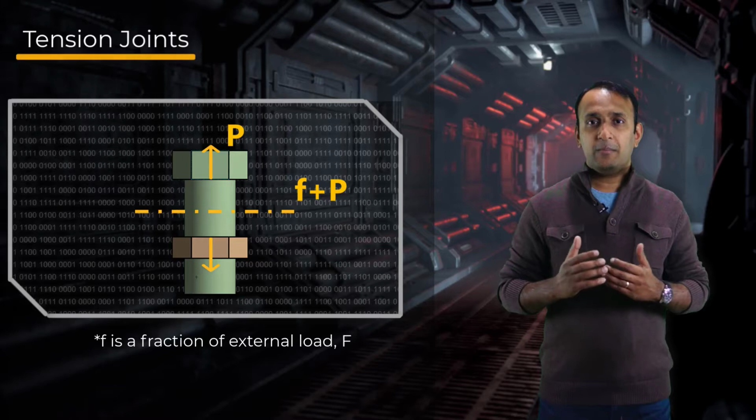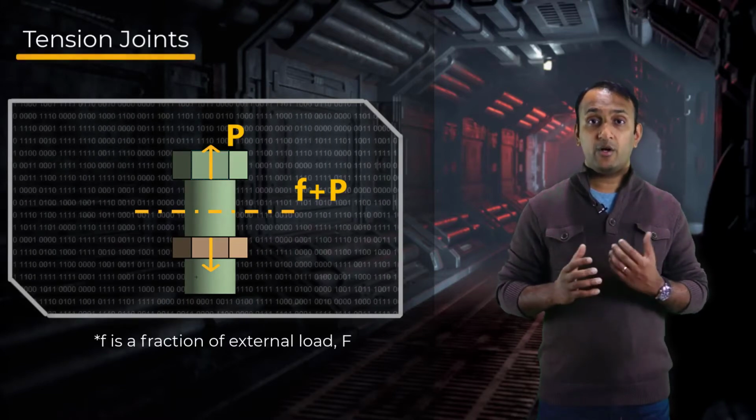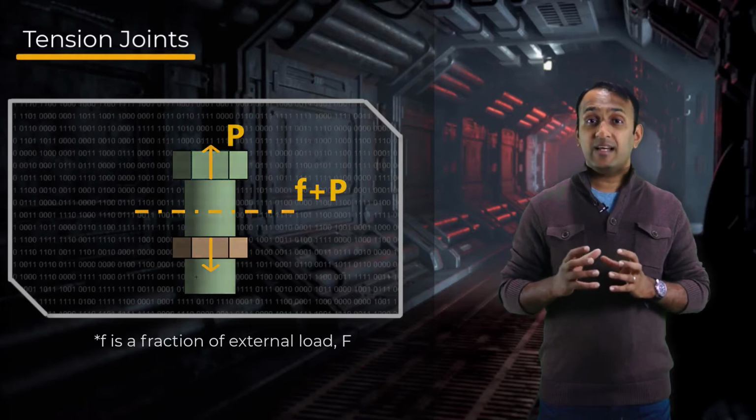It's important to keep in mind that the bolt can experience plastic deformation during operation even if it's within the elastic region during installation. The design requirement for such joints includes proper selection of bolt thread accounting for the maximum external load that it may be subjected to.